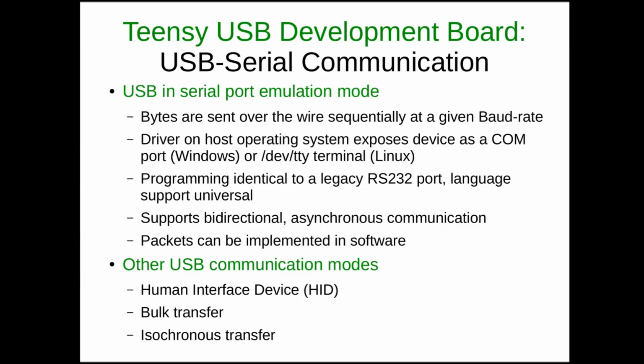There's also bulk transfer. Bulk transfer is what a typical USB flash drive or USB hard drive is going to use. The way that this communication works is that it favors one-directional communication at any given time using large amounts of data. So in other words, when you have a USB hard drive plugged in, generally it's accepted that you're going to either copy a bunch of files to that hard drive, or you're going to be pulling a lot of information off that hard drive, but generally not really doing both methods of communication at once.